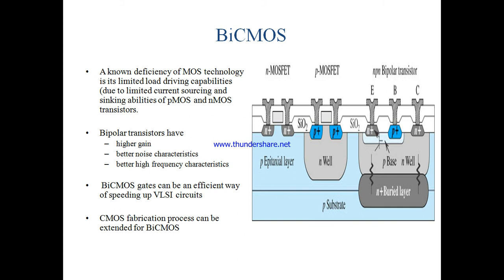In a full bipolar IC, a lightly doped N-type epitaxy layer created on top of the P-type substrate serves as the collector. The collector contact region is doped with a higher concentration of N-type impurities in order to reduce the contact resistance. The base region is created by forming a P-type diffusion in the N-type epitaxy layer, and the heavily doped N-type emitter is formed within this P-type base diffusion area.